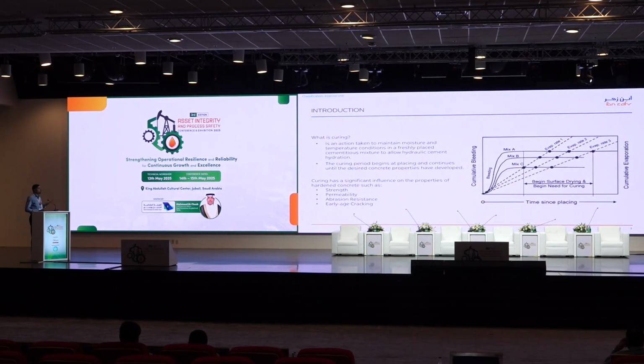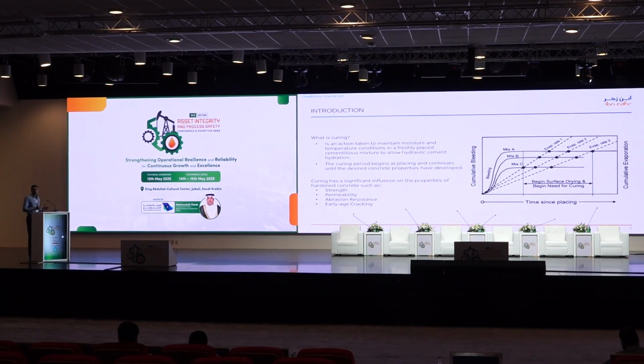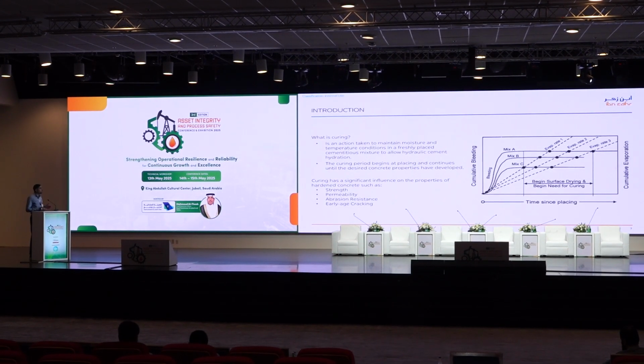So first of all, what is curing? Curing is a process for the concrete which builds its physical and chemical properties: strength, permeability, and abrasion resistance. Curing starts 1 to 3 hours after finishing the bleeding of the concrete.